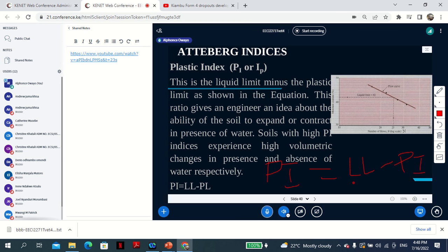But if you go to Westlands towards Kangemi, there is very thick red coffee soil. Red coffee is not so bad, but if you don't design properly, it will cause trouble. Otherwise, in the rest of Nairobi the rock is quite near, and you just find a little layer of black cotton, which you recommend they scrap away, because if you leave it, it's going to cause a lot of trouble.